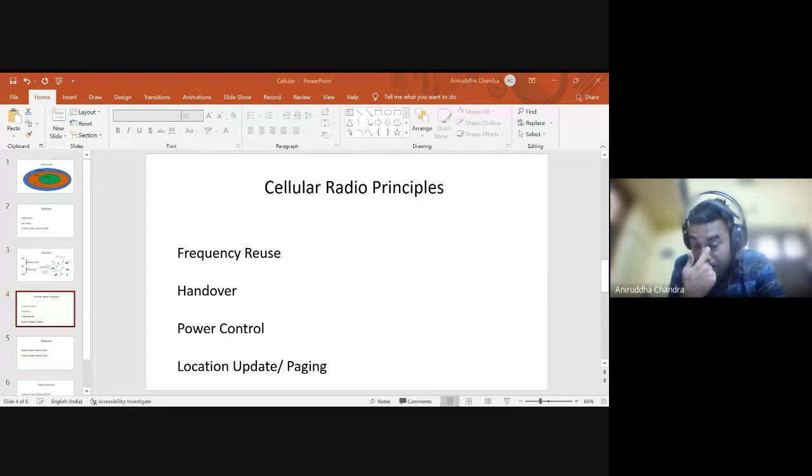For example, we realize something like frequency reuse. So, what is frequency reuse? In the earlier class, I was talking about this. We said that the frequency band is generally divided into several sub bands, and each band is dedicated to a particular user so that they can communicate with the tower. Now, there are only a limited number of such bands available, as regulated by a regulatory authority.